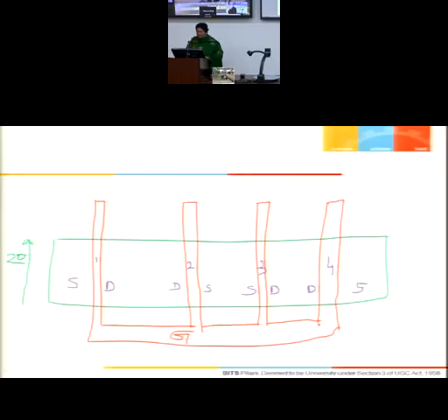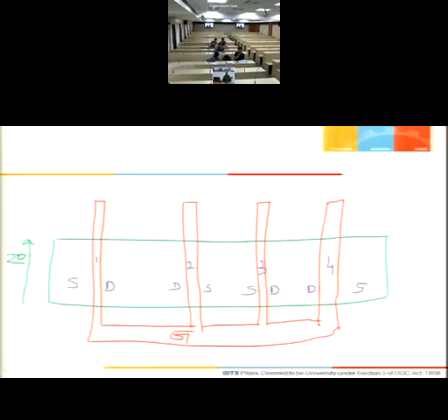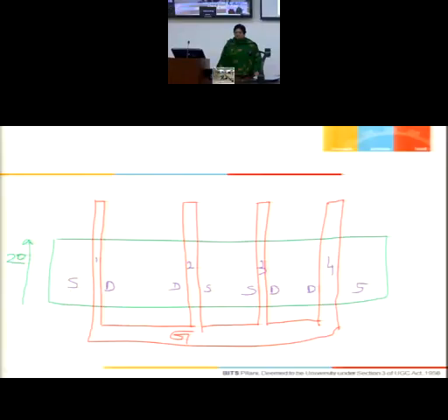How many drain regions do you have? 1 and 2. Purposely I have taken this as a source. I could have started with this as a drain also, but then I would have had 3 drains and 2 sources, and normally drain is the output region. I want less capacitance at the drain region, so I should have a lesser number of areas constituting the drain region. Clear? Goa campus? Yes, ma'am. Okay. Clear?